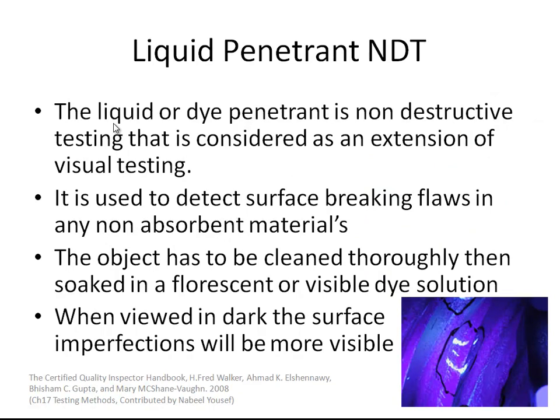The liquid or dye penetrant is a non-destructive testing method that is considered an extension of visual testing, because we're going to use the normal sight to look at the items. Maybe we can look at the item in a dark environment and it will glow in the dark, or maybe using a certain ray or light like ultraviolet to see the imperfections in the object.